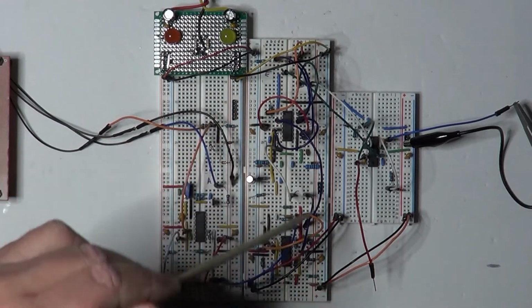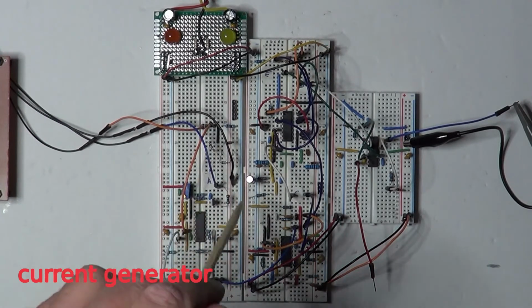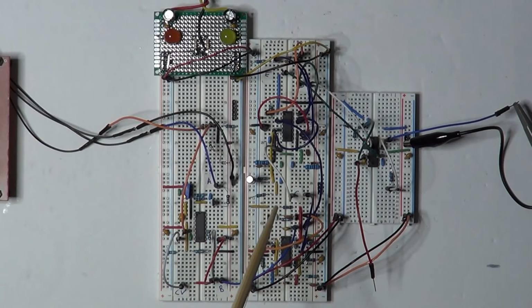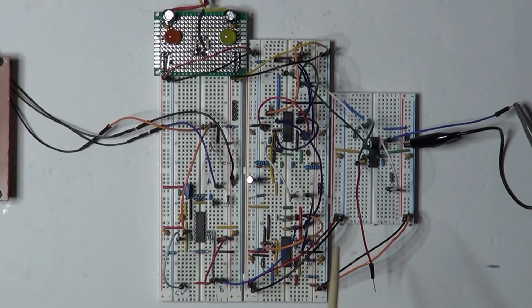The rest of this circuitry here in the central section works on the control voltage generated over here to extract the pulses for the trigger and also to remove the pulse for the last release of the last key on the keyboard. We saw last time that when you press the key and then release it, at the moment of the release there is a change in voltage that causes another pulse, and we want to remove that. So this circuit does that.